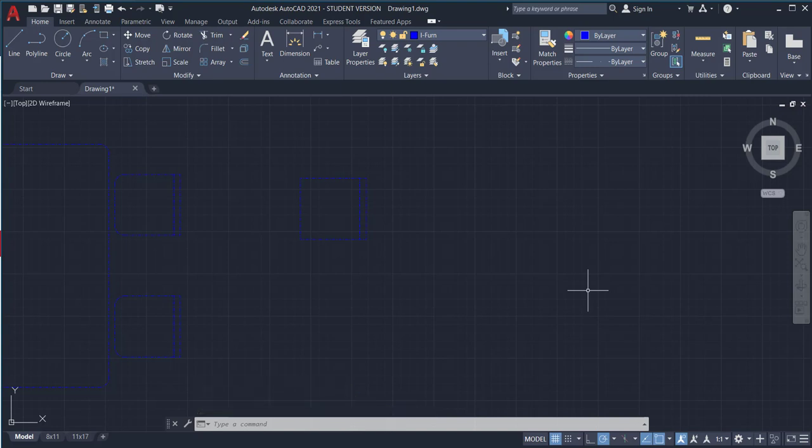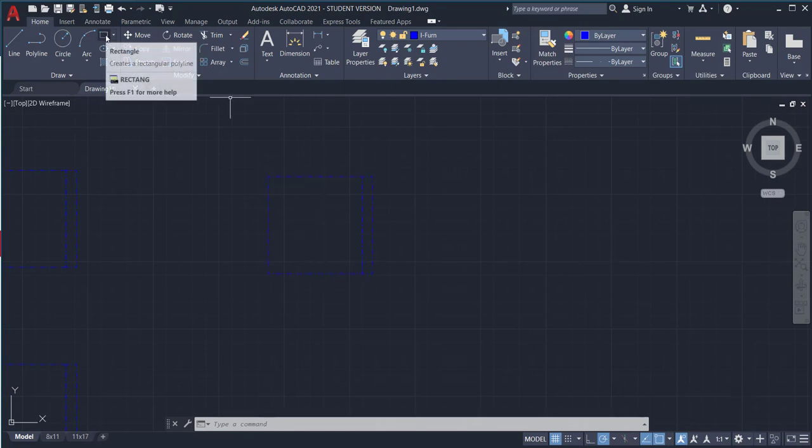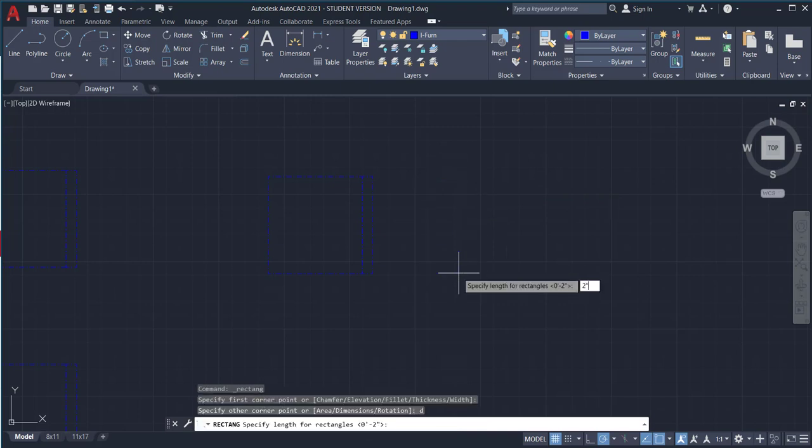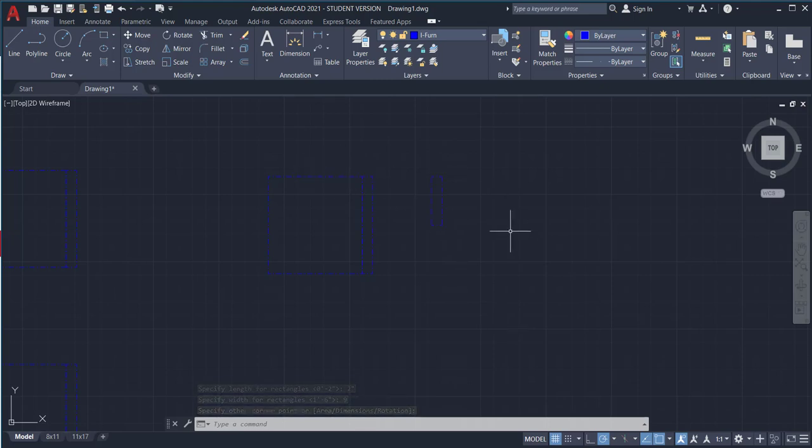This time I'm going to do arms. Those are going to be located kind of half over the edge lines right here. So I'm going to click on rectangle, and I'm just going to draw them right over here. Let's do D for dimension. I'm going to do 2 inches again, and let's say 9 inches. That looks like a pretty decent arm right there. All right, so I want this arm to go right here, but gosh darn, we got it oriented wrong, right?